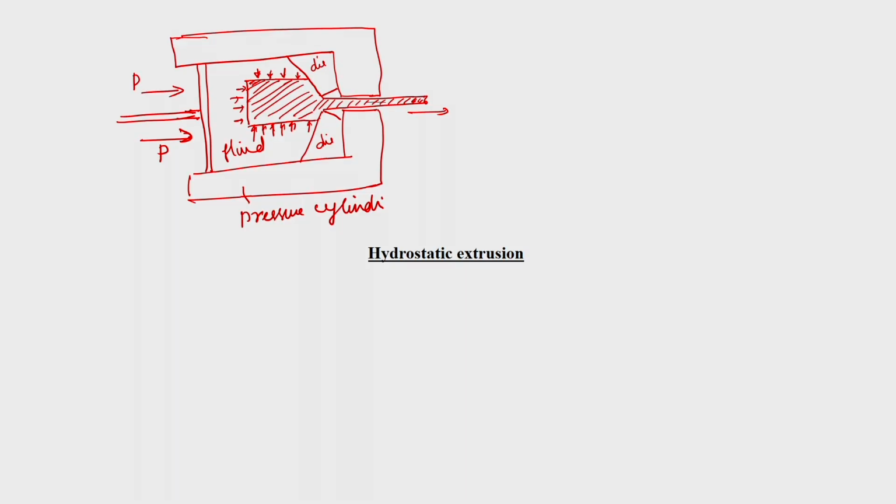And third limitation is that since you are going to fill up some fluid, the temperature at which it can be deformed is also limited. So, normally it is confined to a room temperature or maybe up to something around 100, 150 degrees, because beyond that the fluid whatever you are using at a high pressure, when you apply the high pressure, if the temperature is high, this will decompose and then you may not get what you require. But only thing is that this has to be carried out in a sealed container. That is the biggest problem which people will be facing with hydrostatic extrusion.